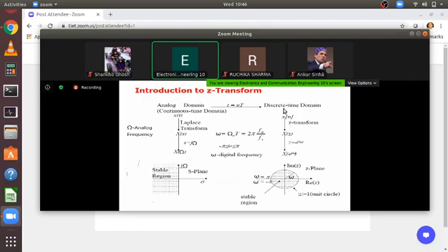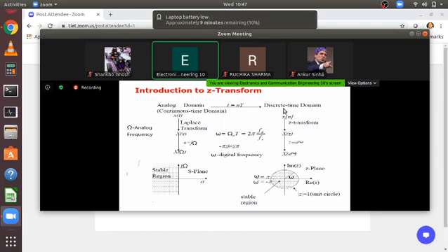X(z). In the continuous time domain, or analog domain, you take the Laplace transform and transform it to X(s), where the parameter is s in the analog domain and the parameter is z in the discrete domain, right? Now s is equal to sigma plus j capital omega.